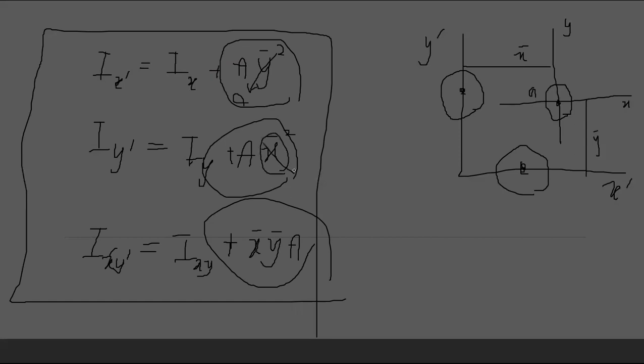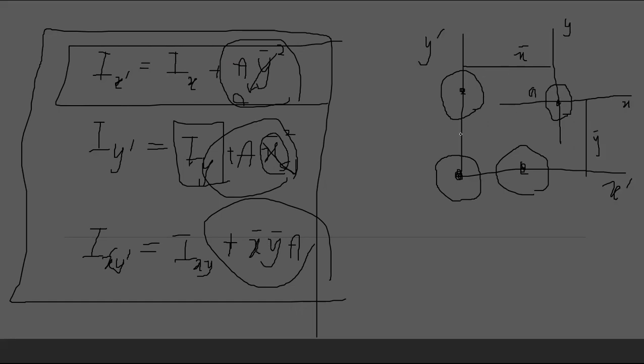That will go to 0. So about y dash, it will be directly given by this, but for x you have to use the parallel axis theorem because y bar is not 0. If one of them is 0, that term will be 0. I hope you understand that. You have to practice this until it gets perfect.